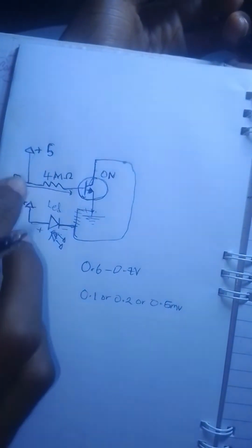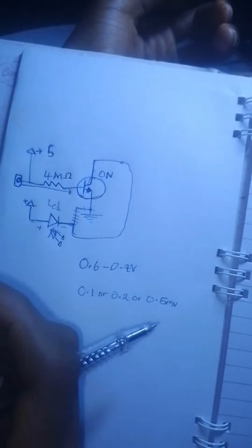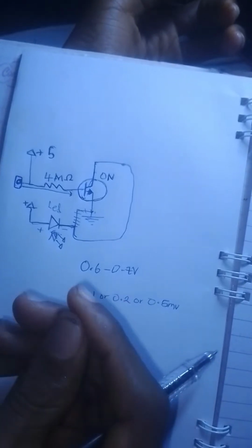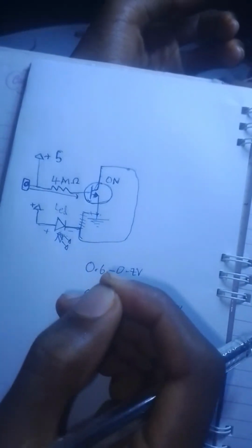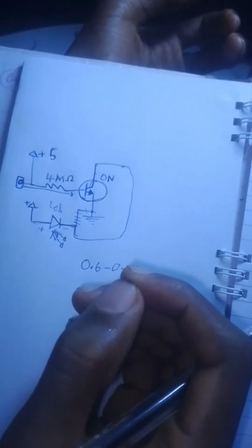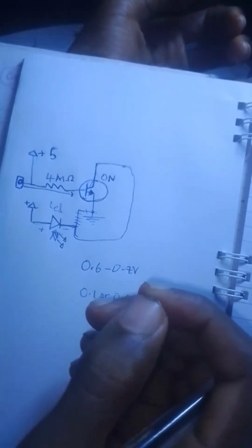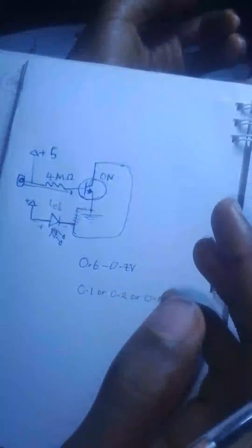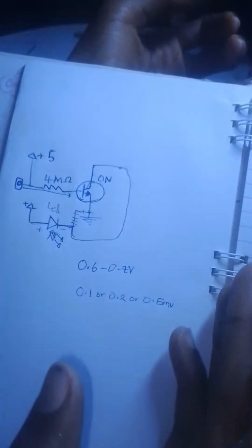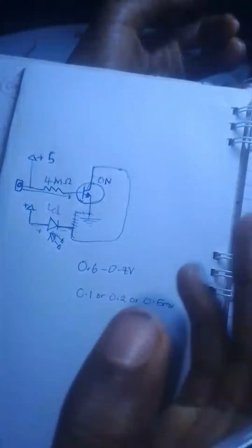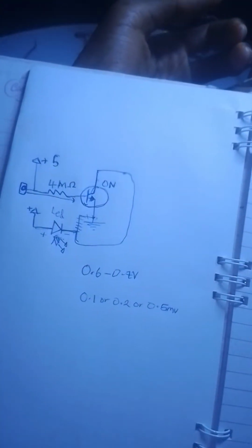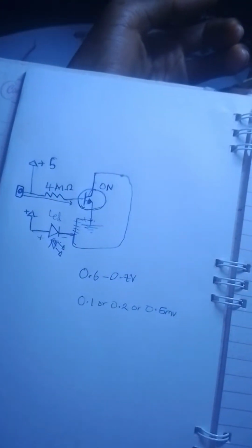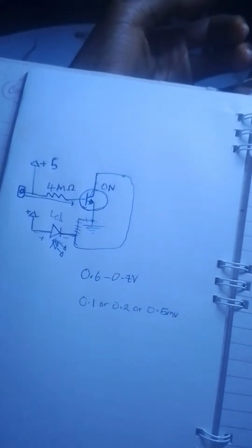Placing our finger on the other side of the resistor will complete the voltage which is needed in the base of the transistor to turn it on completely. Because our body generates a very tiny electric charge, that tiny electric charge is able to complete the voltage and turn the transistor on, and that is why the LED glows, and that is how the touch theory works. If you have any questions, let me know in the comments and I'll explain.